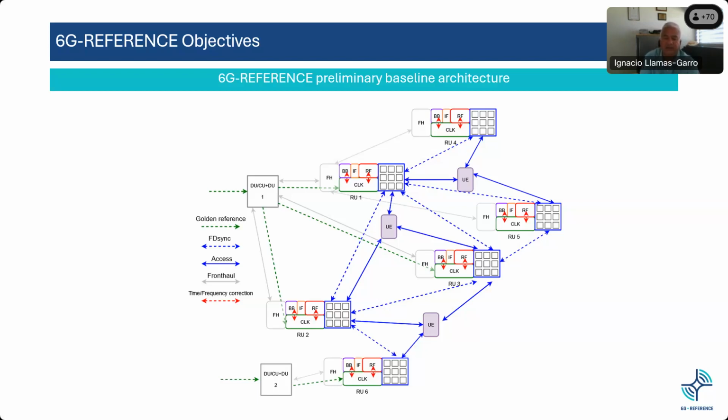The assumption here is that in massive cell-free deployments, this fronthaul and synchronization link will not always rely on fiber, but also on wireless solutions. Case 2 is exemplified by radio units 4 and 5 to the right of the figure that do not have a direct connection from the central unit, but are in fact cascaded to radio unit 1.